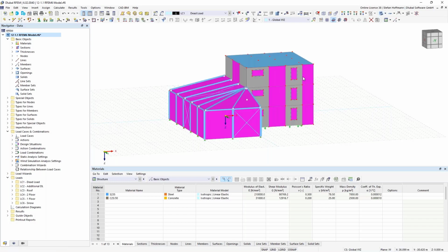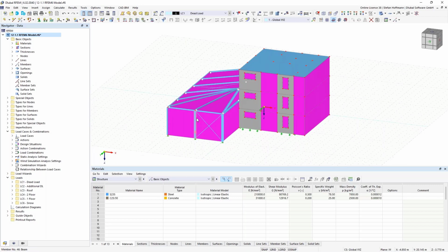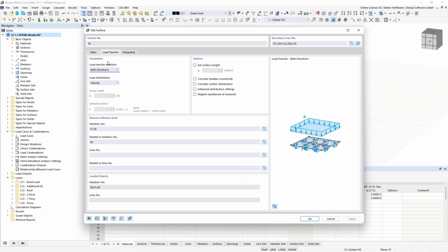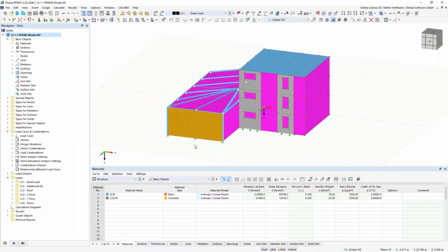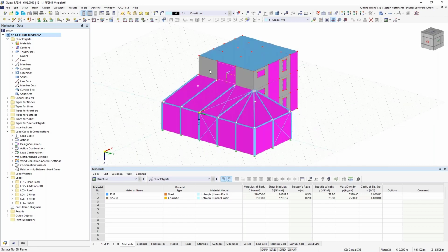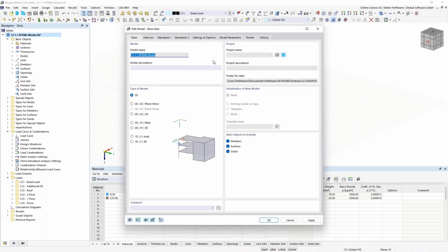And I have used our node transfer surfaces because I will have some facade, which is only giving the wind loads to the structure below and not giving any stiffness into my structure. So for my purpose, I will use those purple surfaces. And I have, of course, also defined if some members are not carrying loads, like those tension members in here, or if my couplings should get some force or not. So this is the stuff I have introduced, and mainly I will now show you what inputs can be done to RWIND and RFEM 6 directly.